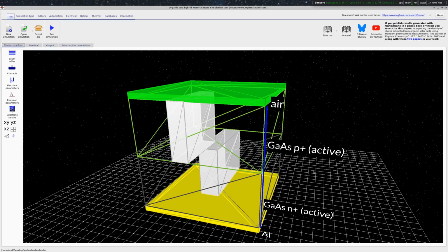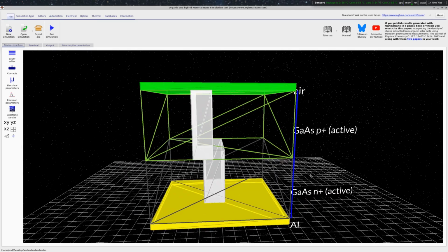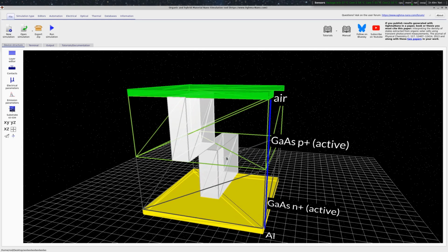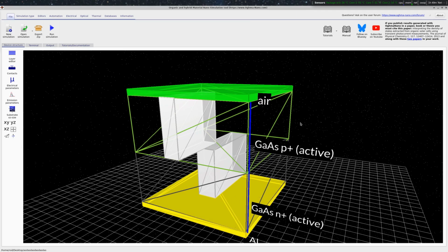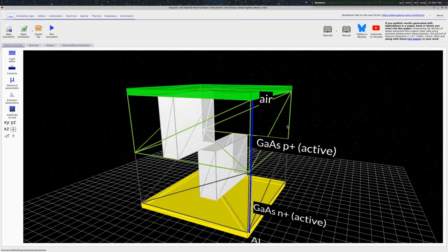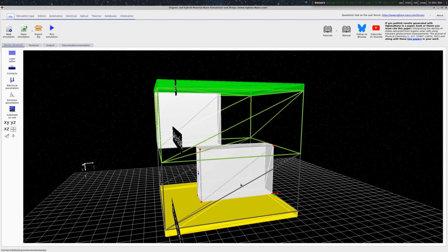And what I put inside this diode, you might say, oh, what are these weird box structures inside it? Well, this represents a defect. This could be, for example, a defect introduced through non-perfect fabrication, or it could be introduced due to degradation in sunlight or some laser striking it, or something like that. But what they are effectively is just two cubes with different electrical properties to the main body of this device, and you can move these cubes around as you like, and set them wherever you want.